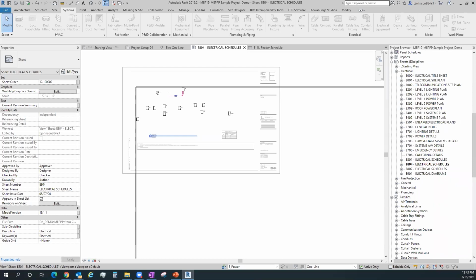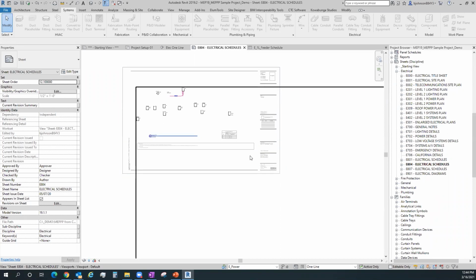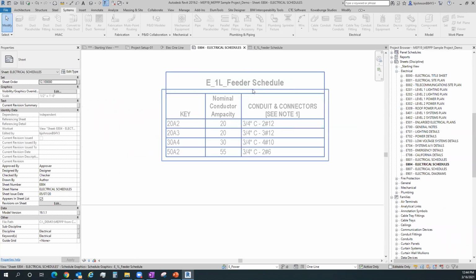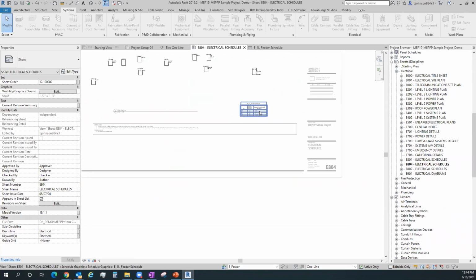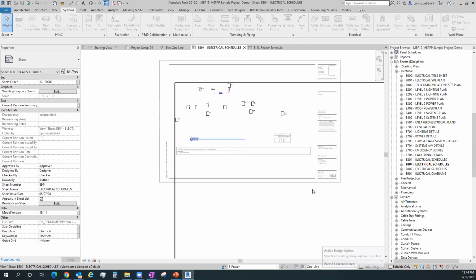Did I answer your questions, Chris? Do we get them all, other than the fact that I don't know why the sheet's gray? It's going to bother me all day. I'm going to find out later why this is doing that. But for right now in the demo and in the webinar, maybe I'll skip that one. But yeah, sheets or views of any kind on sheets, schedules on sheets, it's just the same, even though it's the OneLine view in an alternate universe. I can drag these and drop these all day long, place them exactly how I want on a sheet. No problem whatsoever.